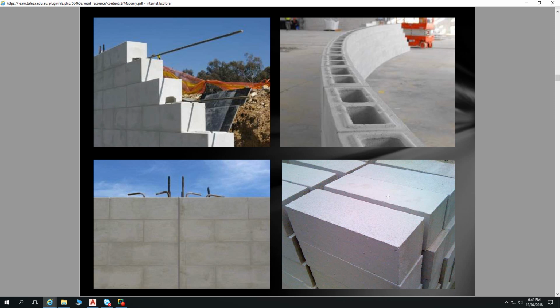The great thing about Besser blocks or concrete blocks is that they can have steel reinforcing added through the cores. And I don't have a Besser block here. They weigh 16 kilos each. They're a bit heavy. But with our Besser blocks there, when I go laying another one on top of that, the accommodations, those channels line up perfectly, even when I've got them staggered half, because there are two accommodations in each.